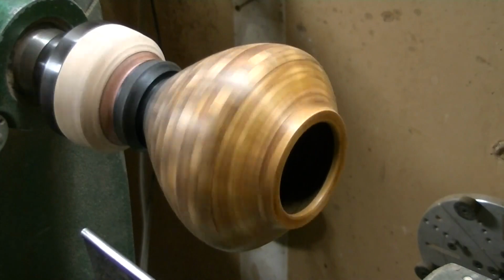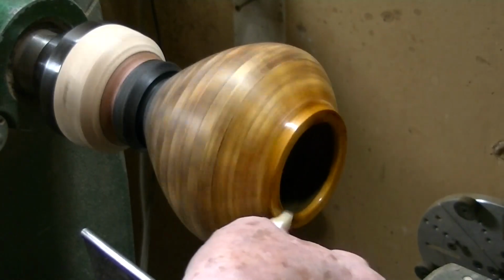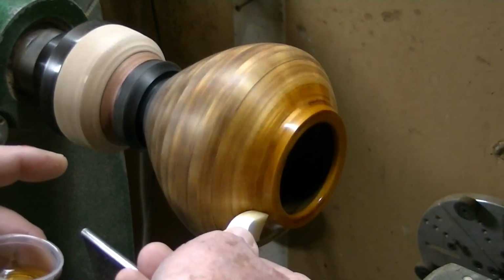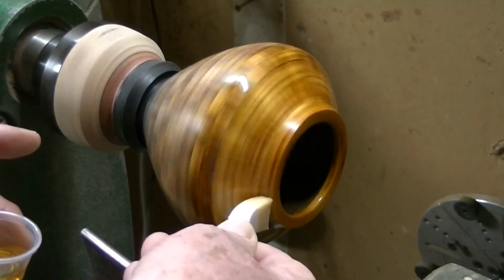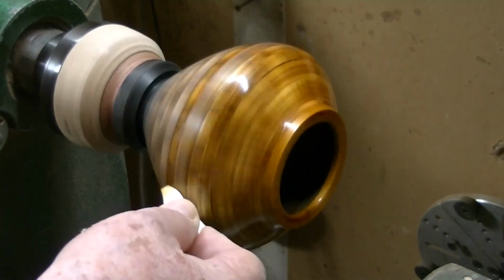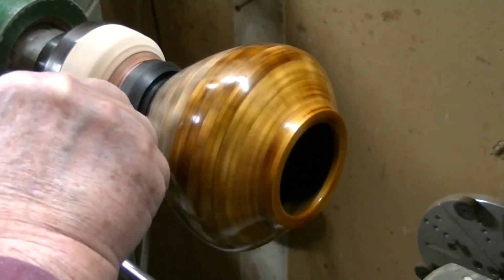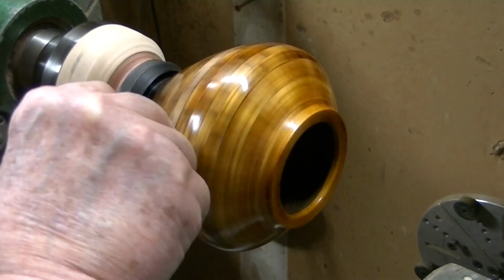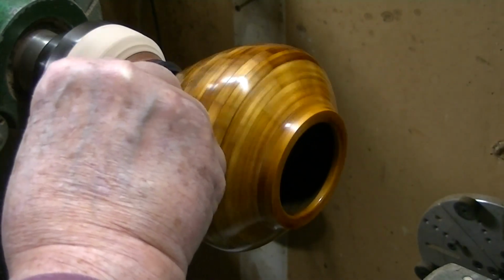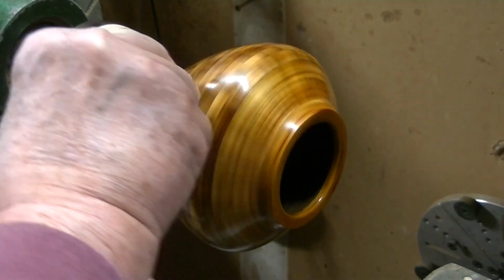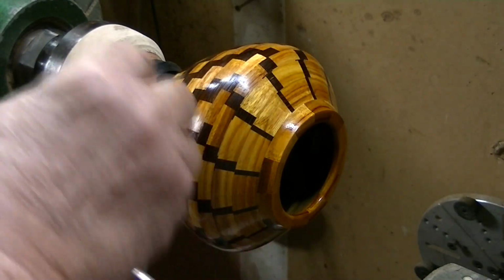I'm going to do this about 5 times. It depends on the wood. If it's very porous, I may do more coats. If it's very dense wood, I might even do less coats. But typically 5 to 8 coats in this process. Apply a coat, sand, apply a coat, sand needs to be done. In the winter here in Northern California, sometimes that's a couple of days between coats due to the moisture content in the air causing the finish to dry much more slowly. So here's the final coat going on, and we'll spread that around. We're going to allow that to dry.